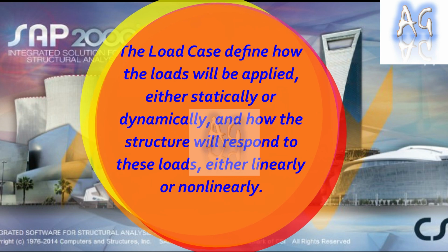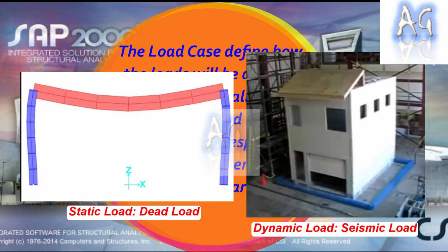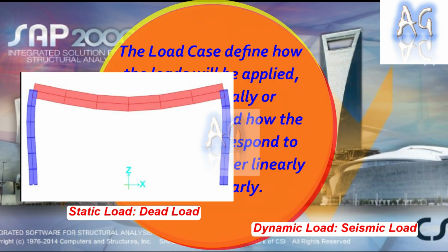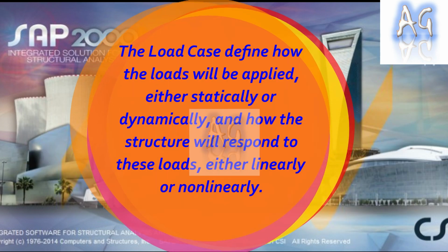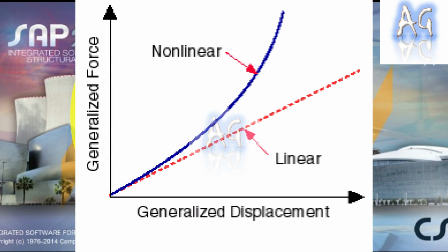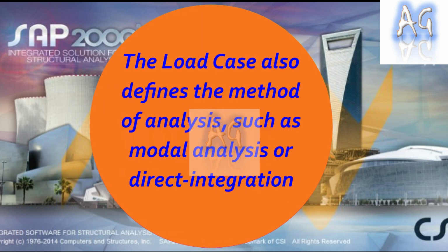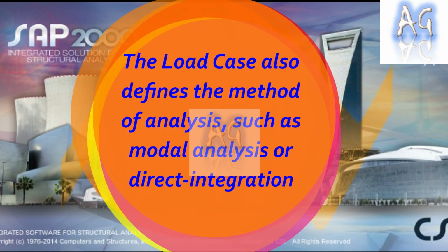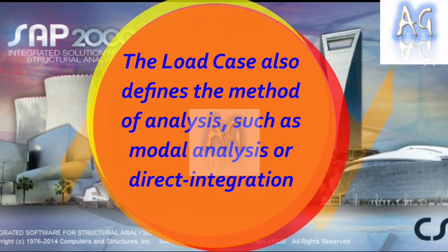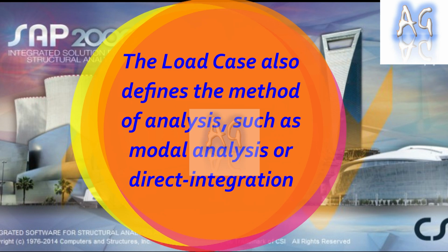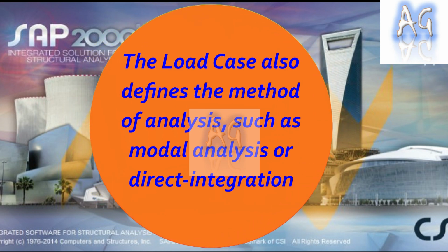That means the load we are applying, whether it is static or dynamic, or how the structure responds, like the structure will behave linearly or non-linearly, and how the analysis is to be performed. That means modally or by direct integration. So all these parameters we have to define in the load case.